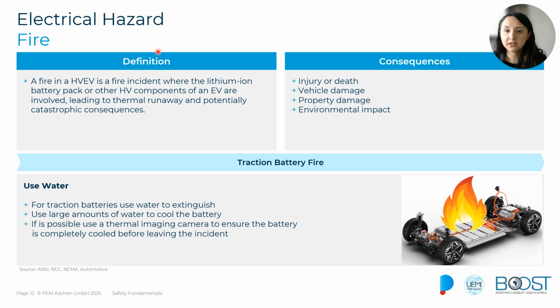Some of the preventive measures that we can have in the case of electrical fires are, for instance, to have proper cooling systems in the systems, to have regular inspections of those systems, as well as, and that is very important, to have firefighting protocols. Of course, everybody has to be trained on how to work in case of a fire there.